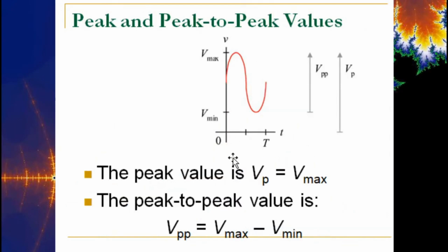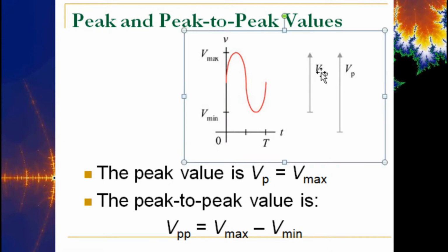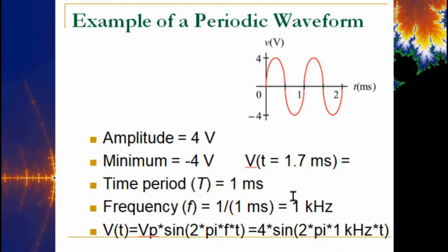As I said, there is a possibility you could ride on a DC offset. And so I think even in your book, they make reference to this peak-to-peak voltage measurement or calculation. You may see something that says the peak-to-peak voltage is 2 times the peak. If we have a signal that looks like this, that is true. However, I don't like these special case things.